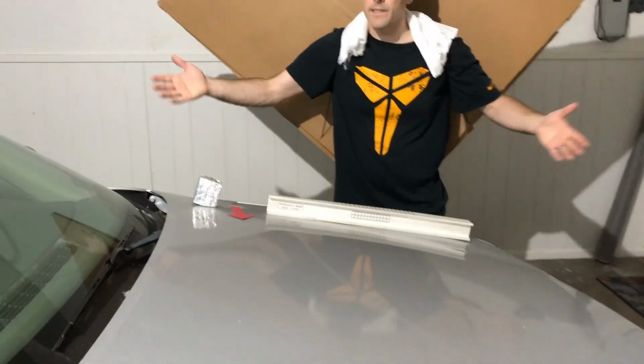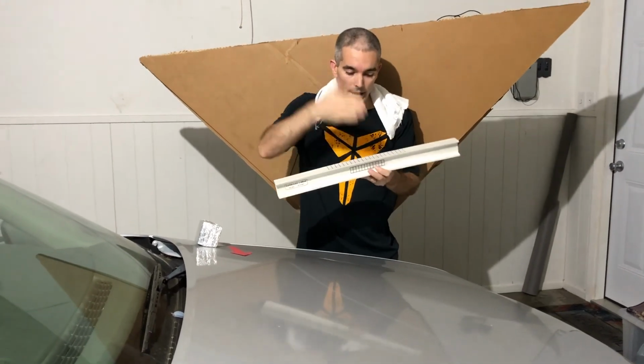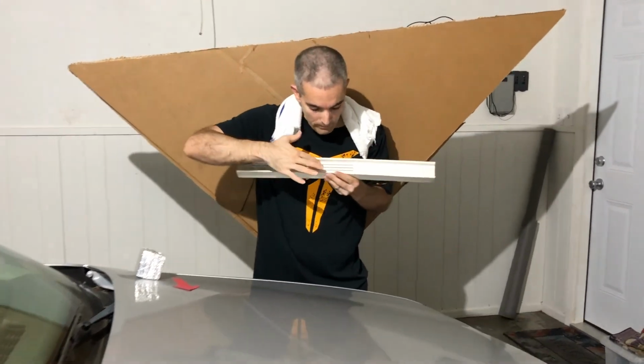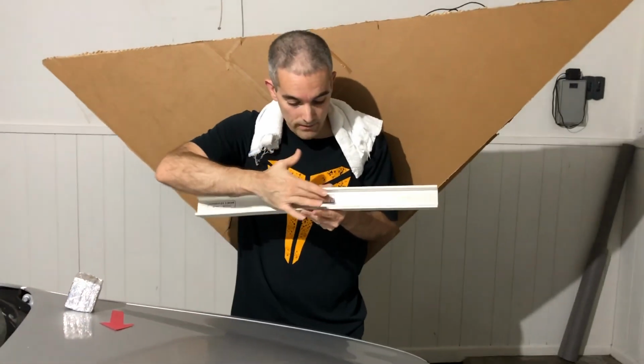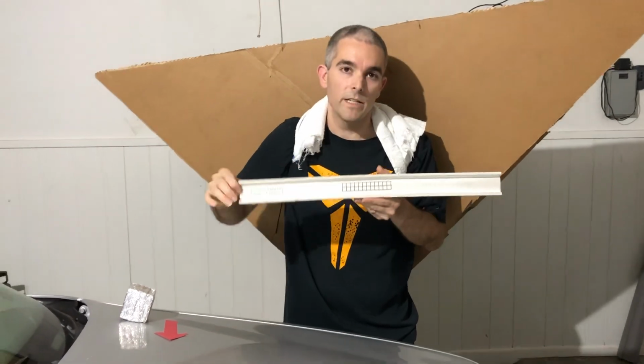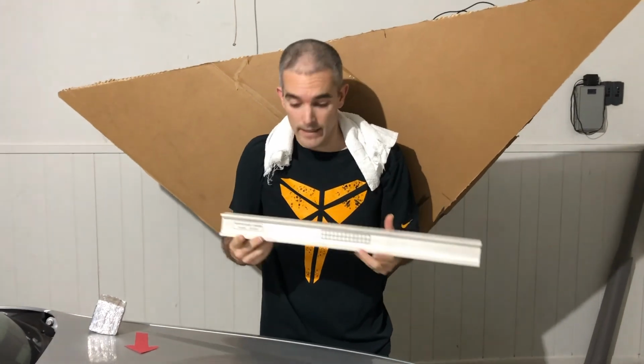We can see even in our car, for instance, much of the surface of the car is not subjected to constant stress. So in a lot of engineering applications, frames, beams are another great example. We might have loads on the beams, they might be bending, we have all kinds of things happening, but these elements here, as we look at them, there's no pressure, there's no horizontal pressure pushing on them, there's no forces that are acting in that direction. So beams are another great example where we commonly see plane stress able to be applied.